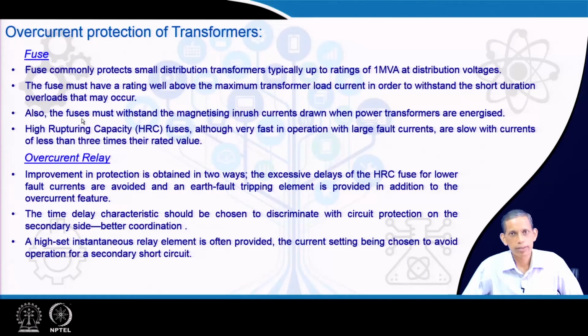So, while deciding the rating of the fuse, its characteristic must address the inrush current, which happens while switching on the transformer at no load or light load condition.